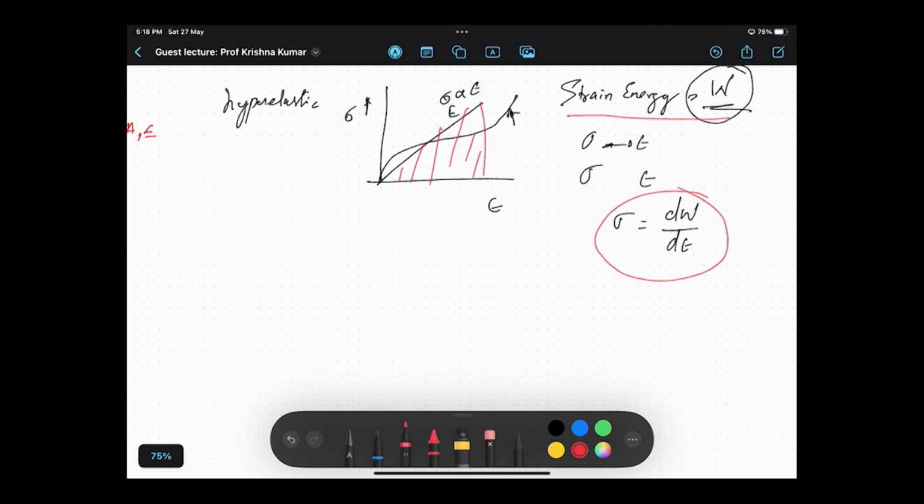Now, again, if you look at papers, they would immediately say W is modeled as a Yeoh model. In fact, most of your keratoconus papers, you would have seen that it's a Yeoh model, Ogden model, Holzapfel HGO model, and so on. So there are a number of them. For tires, we use exactly the same thing. We use the Yeoh model. So Yeoh models are